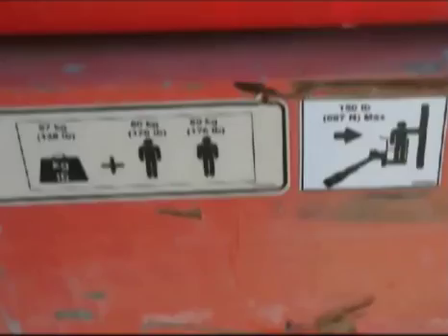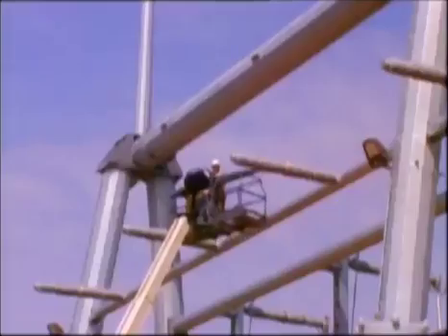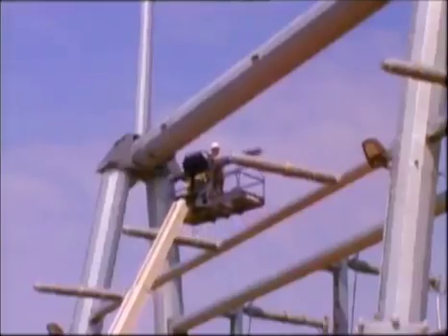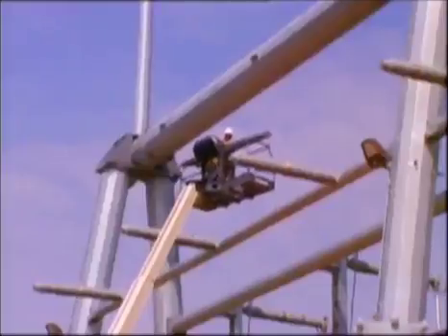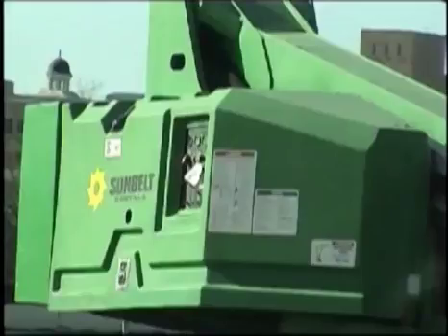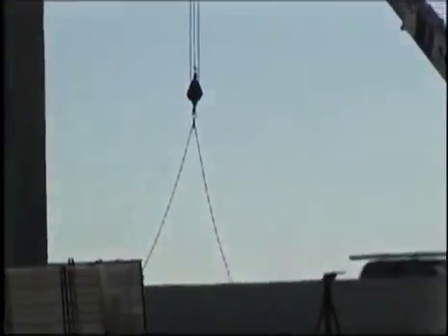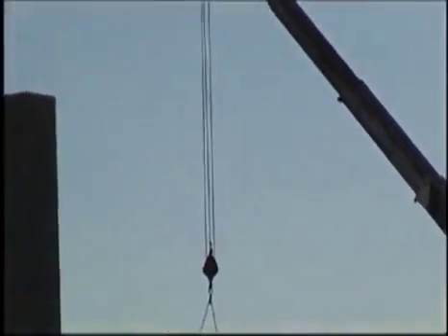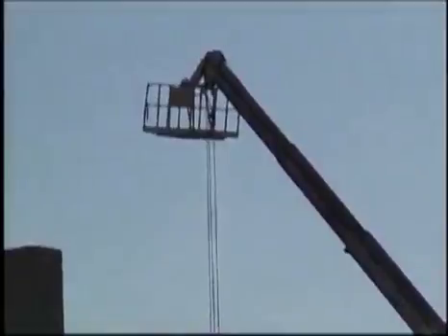The weight of the load should be within the manufacturer's suggested maximum safe working load. Make sure the load is balanced. Always check the loading prior to operating the lift. A manufacturer's load plate is attached to the lift. Never use a lift as a crane unless the manufacturer has designed it to lift loads in such a manner.